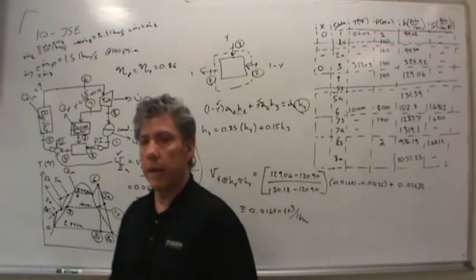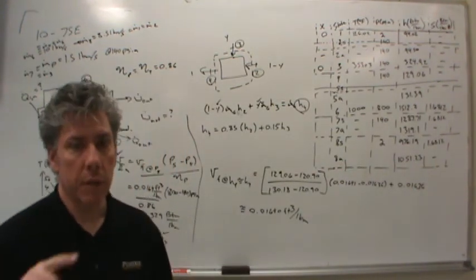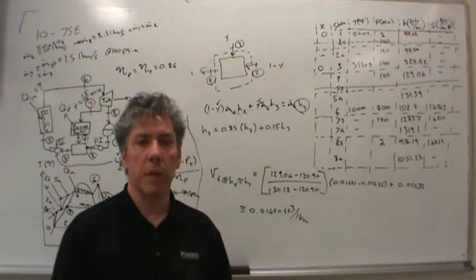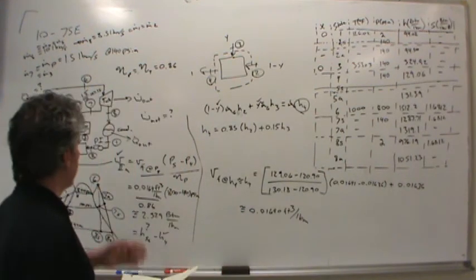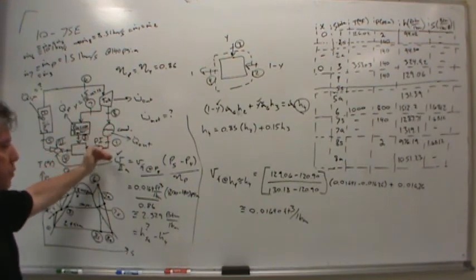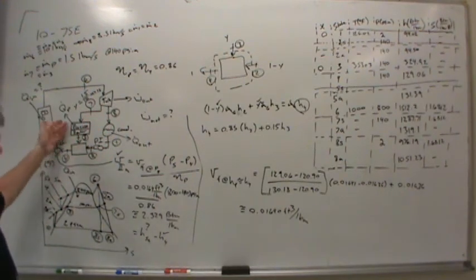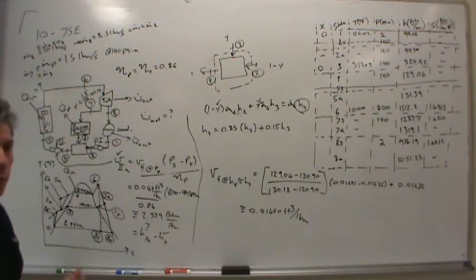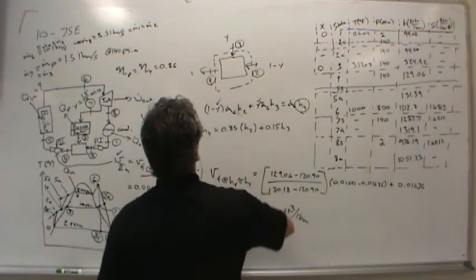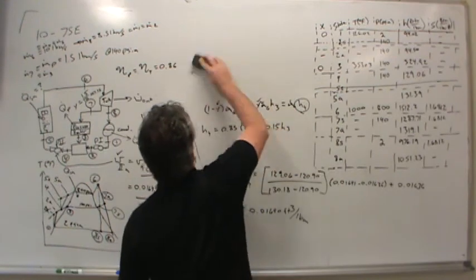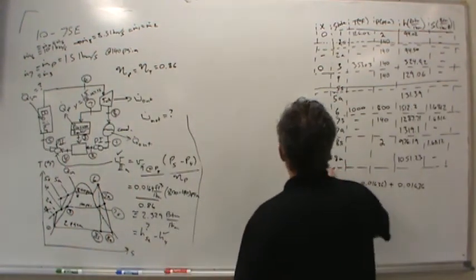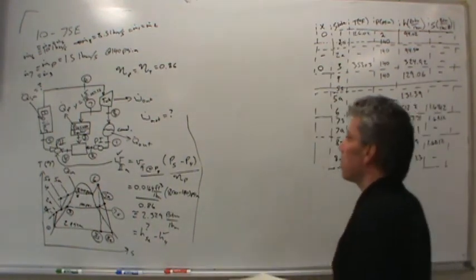Well, the way to solve a cycle problem is always to go around the entire cycle, solving for each and every state, given process knowledge: understanding how the turbines work, how the pumps work, that condensers have saturated liquid coming out of them, same thing with the process heater, and understanding the boilers where all of the mass flows through. And the purpose of all of this is that once you go to answer the questions that were actually posed, you'll find you need all the enthalpies. Well, most of the time.